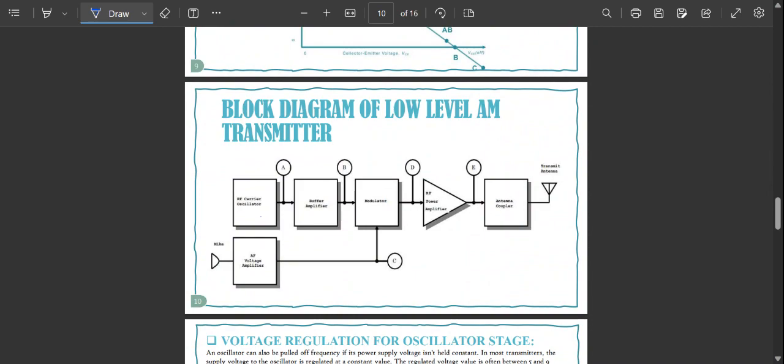The dial or display of a receiver displays the carrier frequency. If the oscillator drifts off frequency, the receiver will be unable to receive the transmitted signal without being readjusted. Worse, if the oscillator drifts into the frequency being used by another radio station, interference occurs. This is very much undesirable.